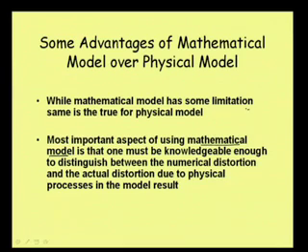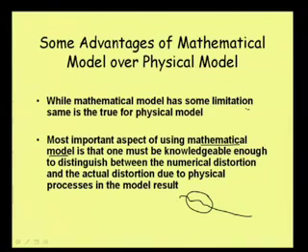there may be some distortion, particularly in fluid problems. Suppose on a surface, we find that somewhere there is some distortion in the computational profile. Now this sort of distortion sometimes may be due to numerical error, but one must know very deeply what the numerical problem can be, and that's why if he just makes the mistake of thinking that in the actual physical problem also this sort of disturbance will be there, then he will end up making an error. So this is very important.